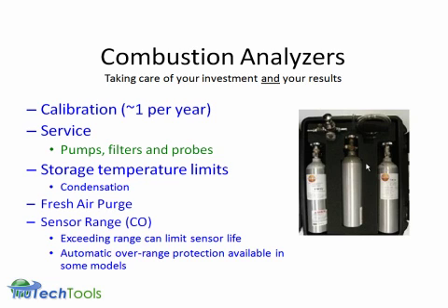Combustion analyzers require a calibration about one time a year. You also want to have the pumps, filters, and probes checked. With all analyzers, as long as you drain the moisture out, you don't have to be too concerned with storing it in cold temperatures. But you've got to realize that an analyzer warms up. Especially if it's very cold, it is going to impact its response time. So you want to take that into consideration. We really recommend you keep it up in the front of your cab and let it warm up as you drive to your first call in the morning.